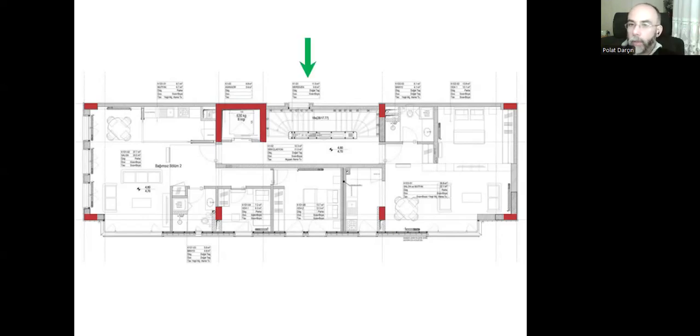What happens during the earthquake? Earthquake is a lateral force. It will push the building to move sideways, but there is an imbalance weight-wise. We know that shear walls and columns made out of reinforced concrete are very heavy objects.